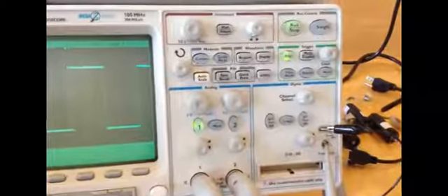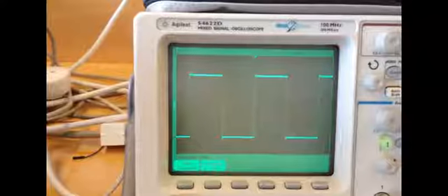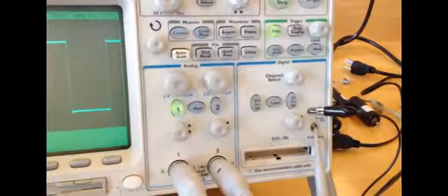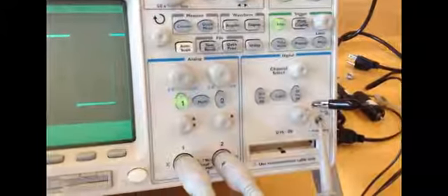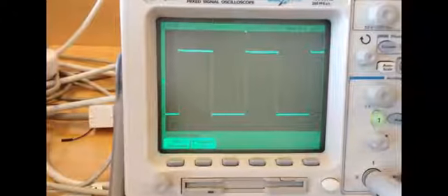So I don't have to go through all these knobs and set them so that I can see a nice signal like this. What I see here is a square wave signal, which is normally used for calibration, and it's a built-in signal inside the oscilloscope. I just used it to show you how a signal is going to be captured by the oscilloscope.